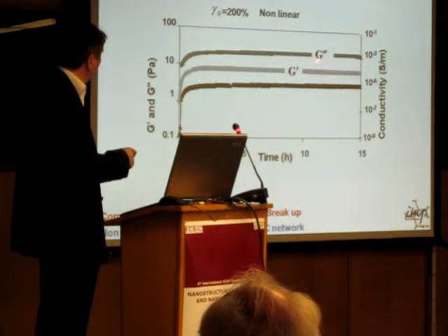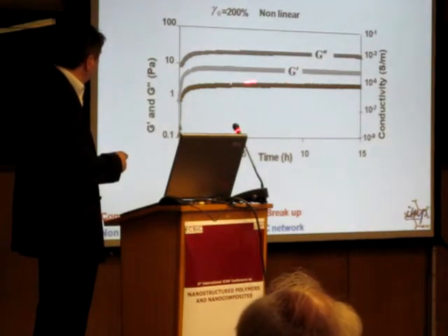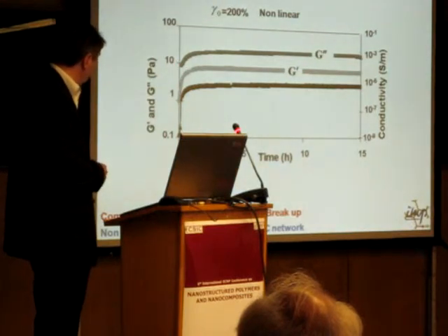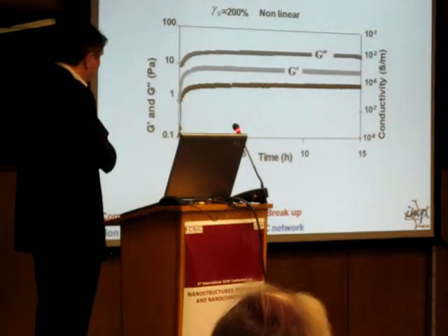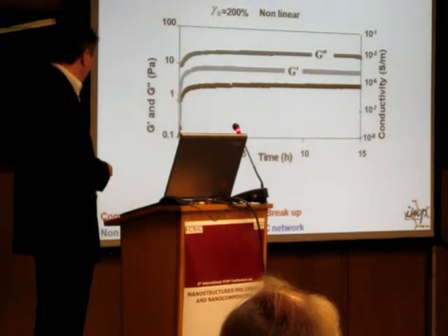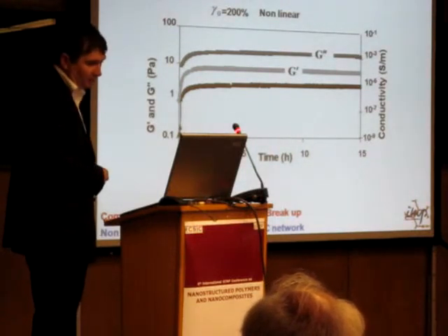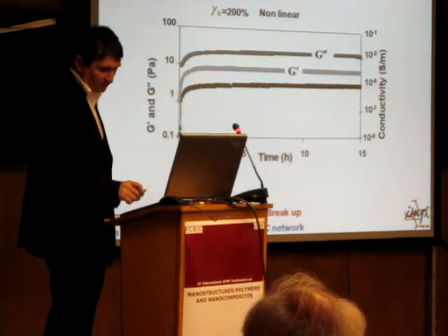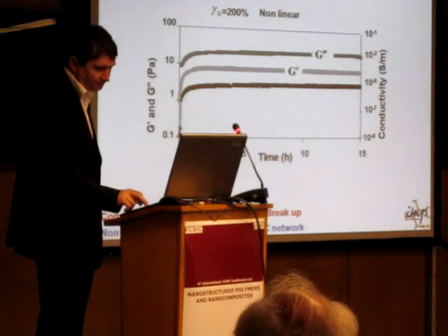And G prime is lower than G double prime. At this deformation, I am still in the liquid viscoelastic regime. So at this deformation, actually, I have a competition between clustering and breakup of these clusters, because I am in the non-linear regime.